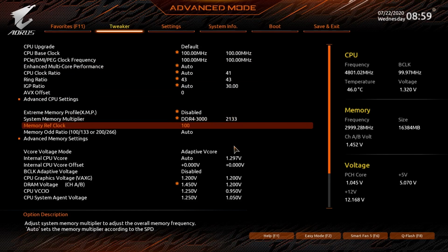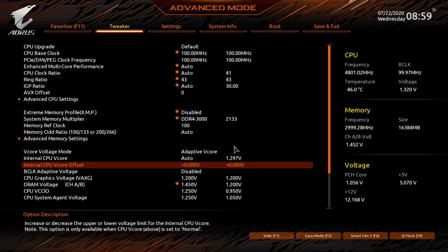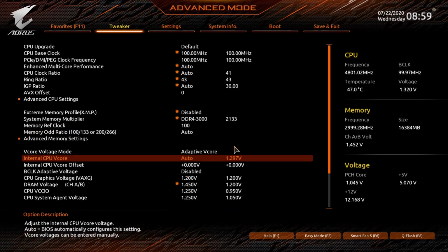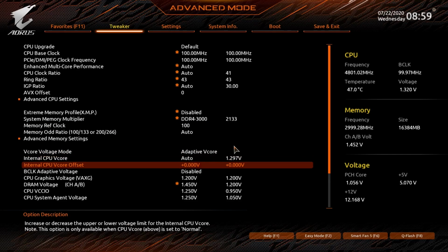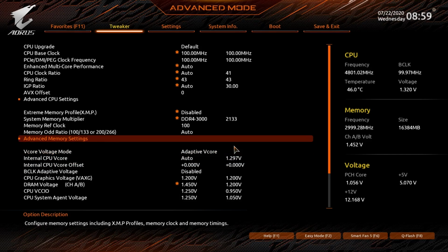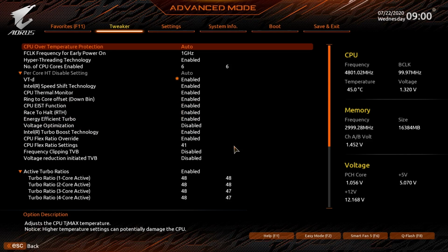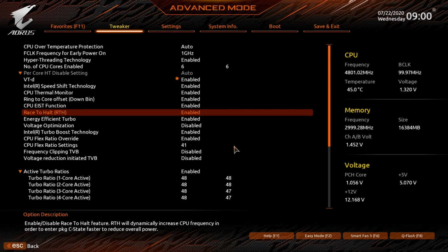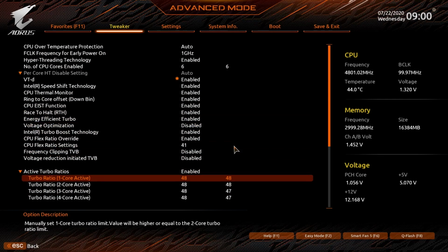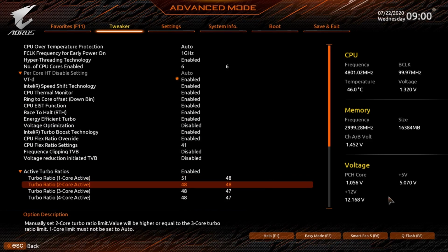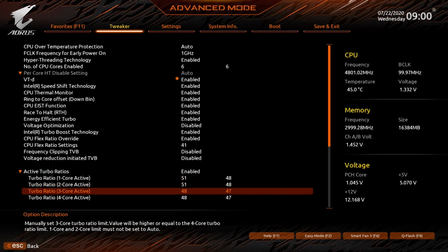We're going to go ahead and change the CPU clock ratio. We're going to see if we can get into Windows at 5.1. We're not going to do anything with the voltage because we're doing an adaptive vCore, and when we change the turbo frequency, it might send the CPU more voltage. We definitely don't want to mess with that yet until we see what voltage it's going to send the CPU in auto. Alright, so we'll go down here and try 5.1.